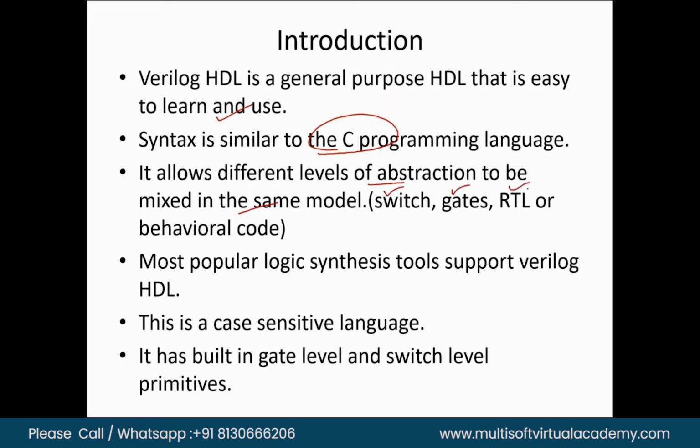These are the three different methods which I already told. One more feasibility here is that you can mix your gate level with data flow modeling. So gate level or structural modeling can be mixed with data flow modeling, but not with behavioral modeling. This mixing is also possible in Verilog.